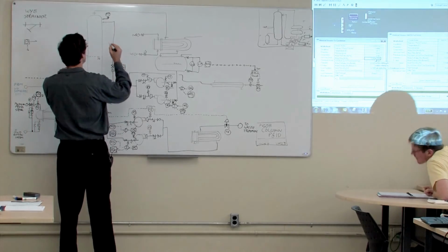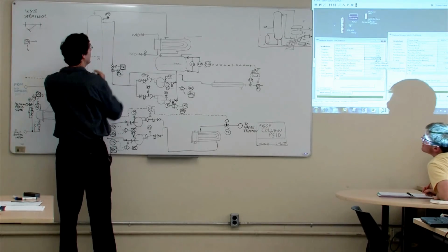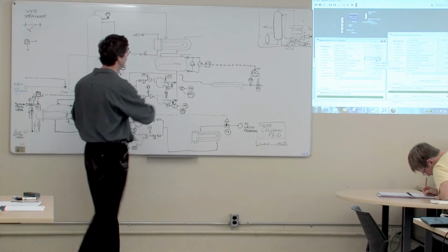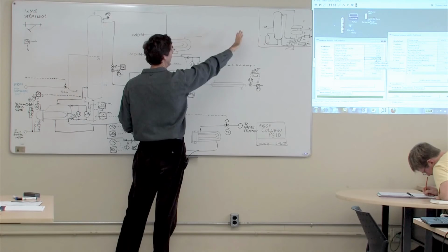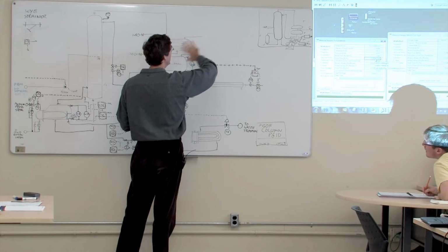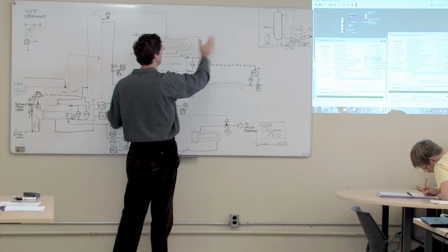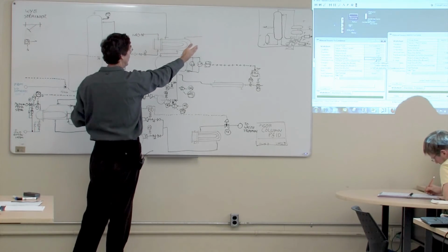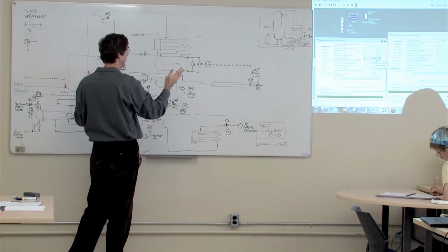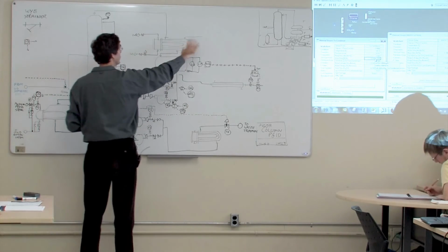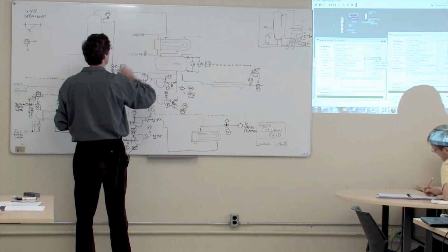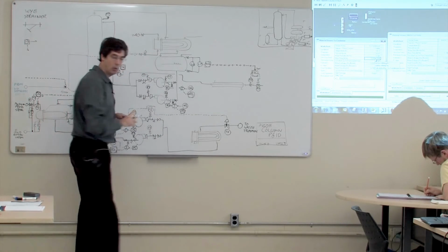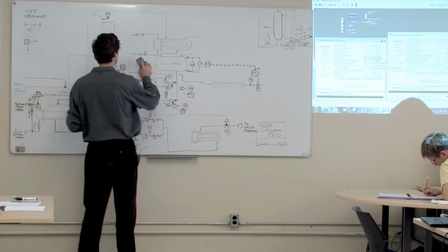composition and pressure. Okay, so the easiest way to do the pressure, as long as if your vapor flow rate was really a huge value, so that if you suddenly opened a valve up, you could depressurize the column, then you might want to put the pressure control on the vent rates. But that's not the case. That flow rate is really, really small. So the way to do this one is to put the pressure control on the cooling water, and I'm going to cascade that too.